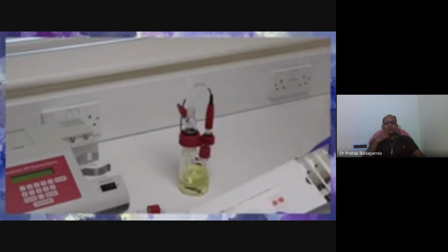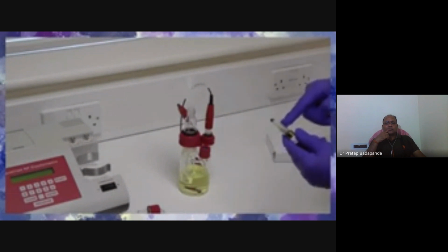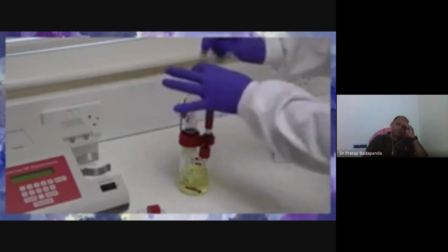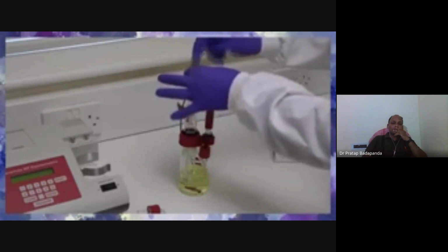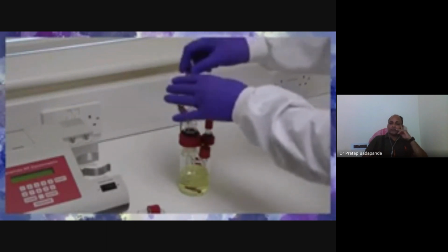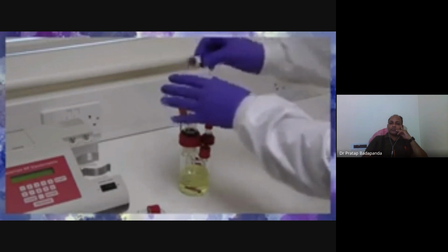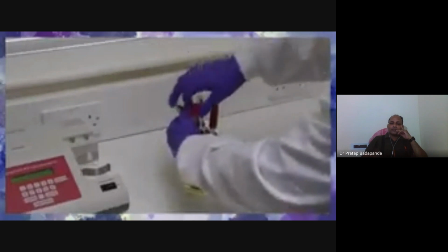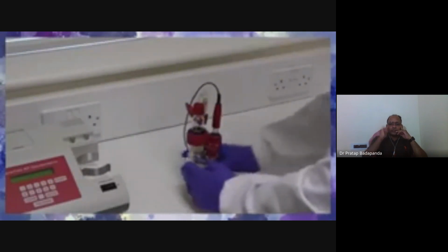Take the cathode reagent, snap the vial, which has a safety snapper already fitted, and pour the reagent into the inner chamber of the generator electrode. Reconnect the drying tube, relocate the glassware onto the Aquamax KF moisture meter, and connect the electrode leads onto the appropriate sockets.